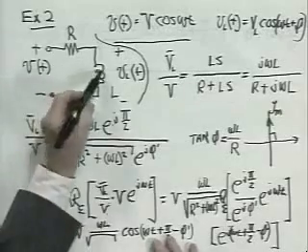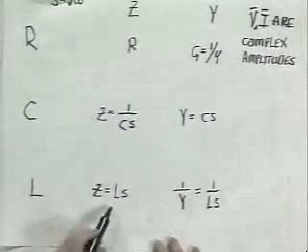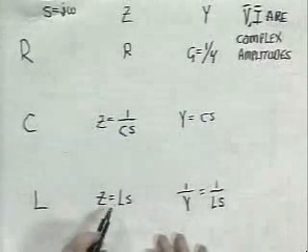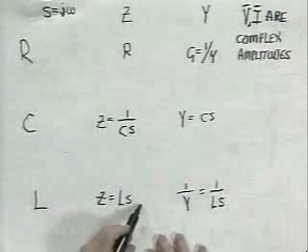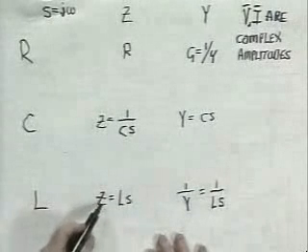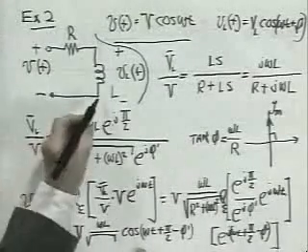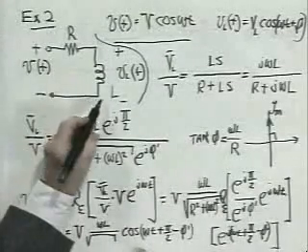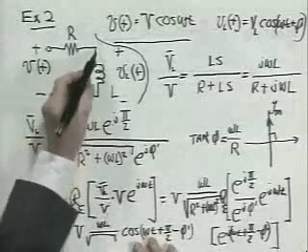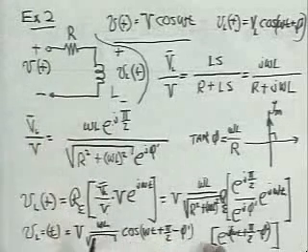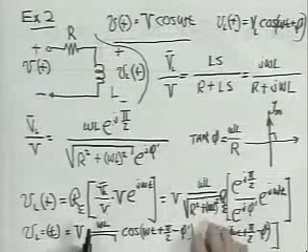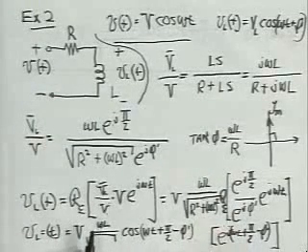Does that correspond? Well, remember back to the impedance of the inductor. It varies as j omega L. So as I go to lower and lower frequencies, the impedance of that inductor gets smaller and smaller until you get to the point where there's no voltage left to cross it. That corresponds to this amplitude factor going to 0.